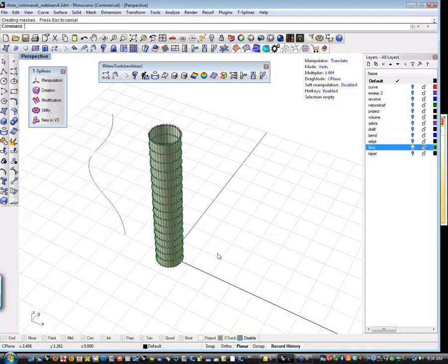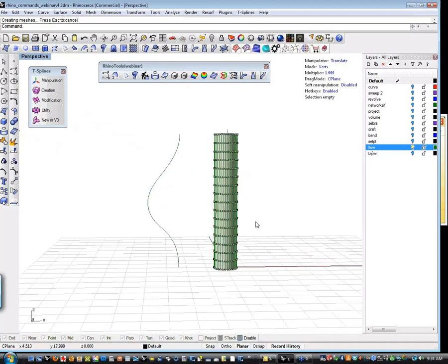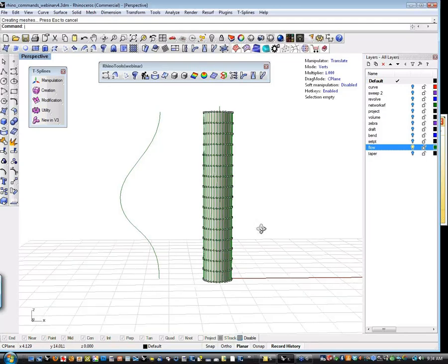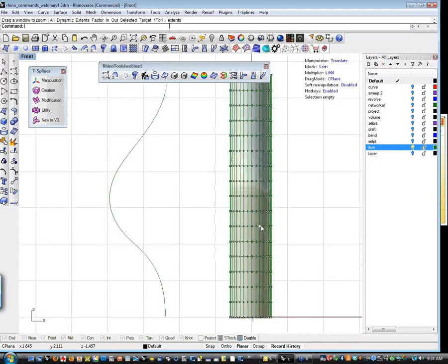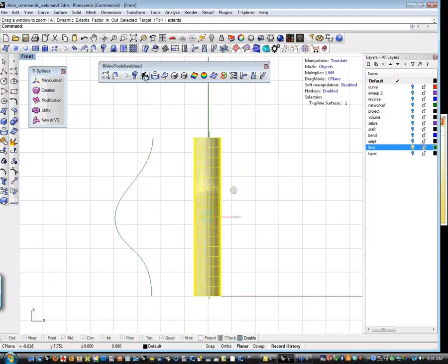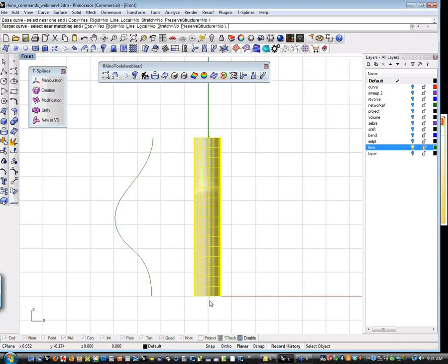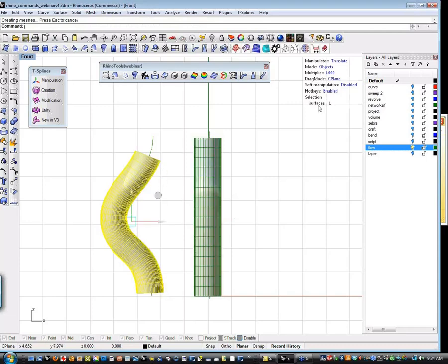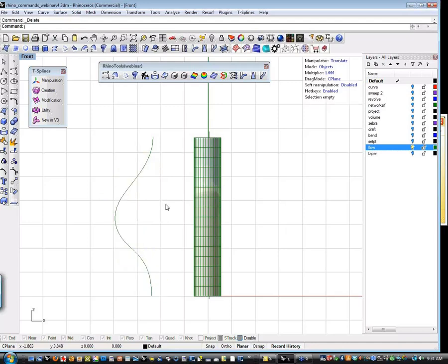The next thing that we're going to look at is flow. And again, this is a UDT command. And it's super, super powerful, and I'll show it in the front view so that it's really obvious what's going on here. Again, it will work if I pick this object and flow it. It'll flow, but the result is going to be a NURBS object. So that's not what I want. I want to be able to maintain the editability of this.